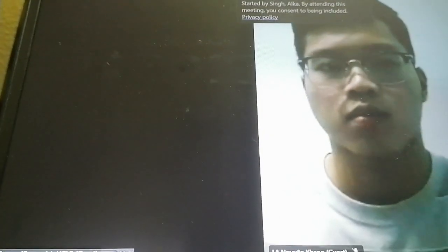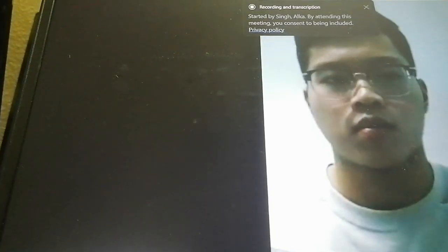So one part of the distributed architecture is a device interface. The device interface allows you to interact with either emulated or real devices. Basically you can connect with a DNP3 or a 2030.5 device. You can send the measurements to the application using the GridAPPS-D API, or you can receive the control command from the applications and send it to any device.